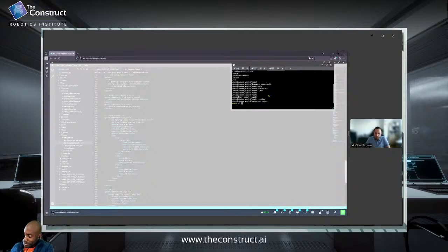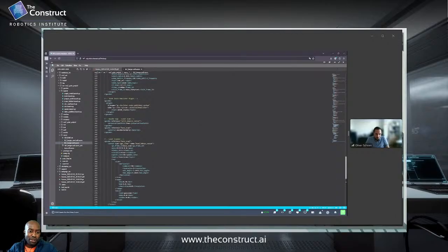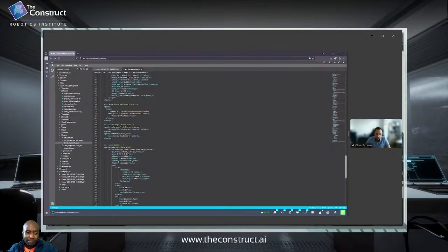The next one that I want to ask is with regards to the joint state publisher. You do have to use the joint state publisher when you are running the real robot. Why is it that you don't have to use it when you are using simulation, for example?